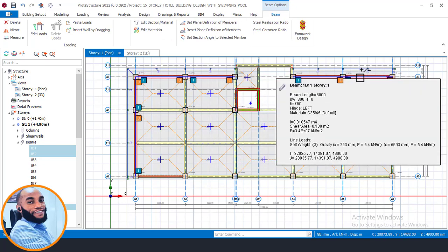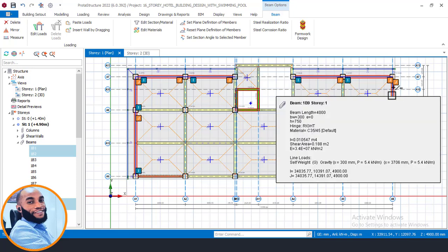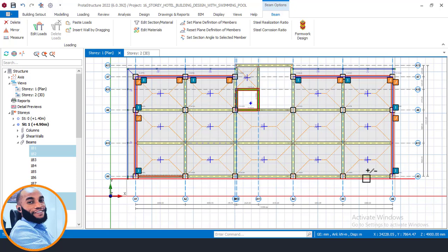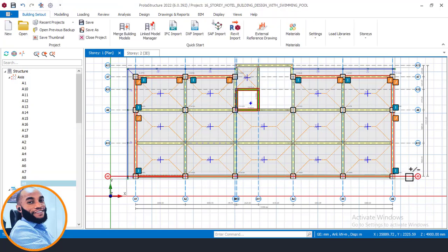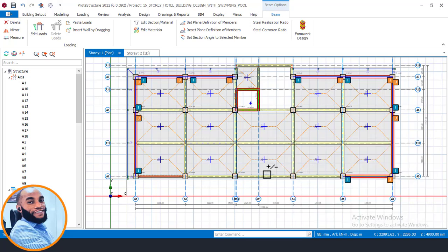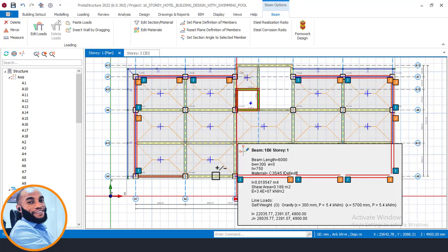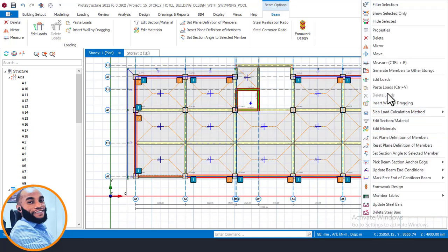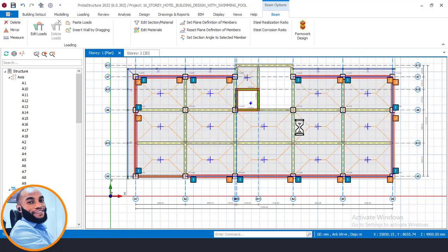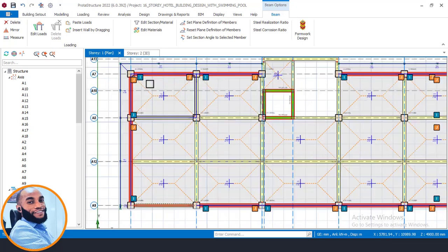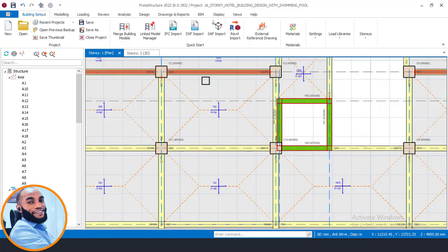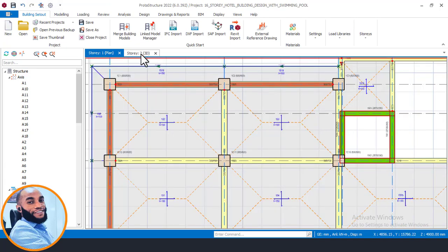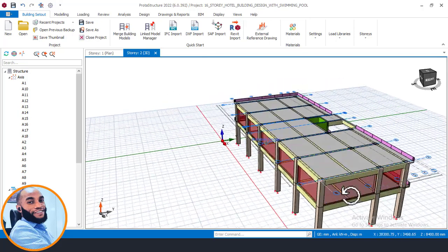I'll click on all the perimeter beams, click here and here and then here. Sorry, not the grid line but the beams alone. Okay, and I'll right click here and say paste load. I'll say yes, paste load. Now you can see that all the load is now pasted. Once you see your beam being hashed, you can see that this beam that is hashed is carrying wall load. Now check on our 3D view, you see that all the perimeter beams now have wall load.